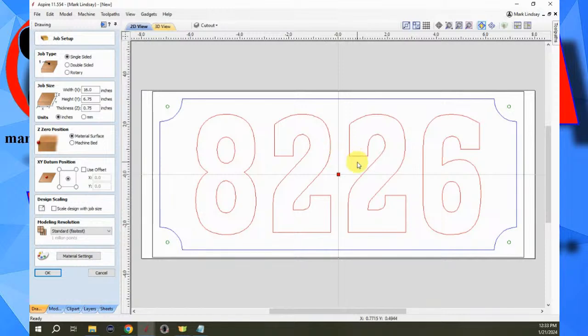All you can do is delete it and create a new one. So if you discover a mistake down the road, maybe these should have been slightly larger drill holes, you can load up the file just like I'm doing right here, increase the size of those holes, then save that as a template. But once you've created a template, that template cannot be edited. That's why it's putting me into job setup.